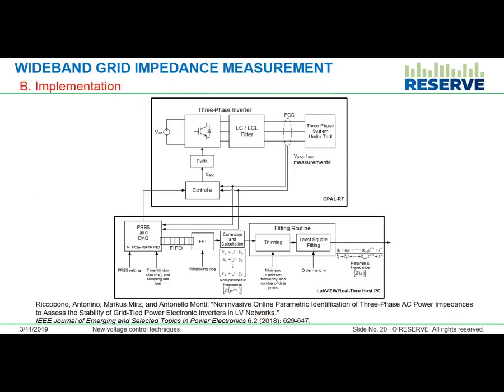So here is just an implementation that we did in LabVIEW. There is an FPGA in the National Instruments LabVIEW environment where you can do all these sophisticated calculations. The noise is injected into the controller, and the measurements are obtained simultaneously as you inject the noise, and then you have the Fourier transform calculation and impedance calculation. And if you want, you could do some complex curve fitting to find out the parametric transfer function, just to see what the transfer function is.